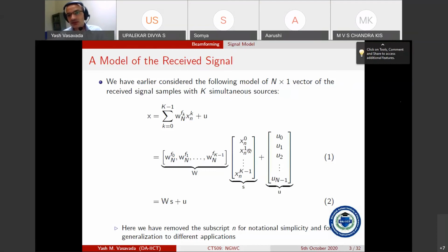And these two users are independent users. So they can transmit any symbol anytime. They don't worry about what the other user is transmitting. And so for each of these 4 QPSK symbols, there are 4 possibilities of x1. And so you will see that there are a total of 16 possibilities of vector S.